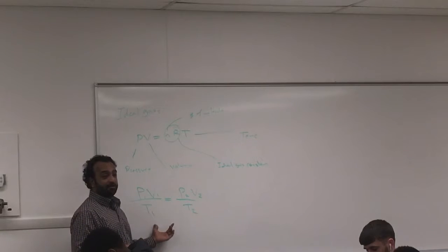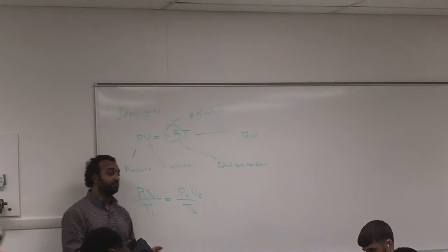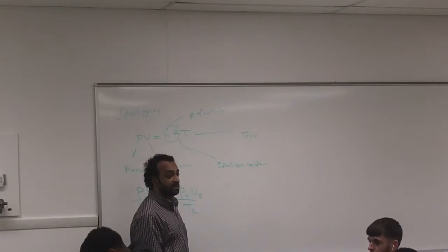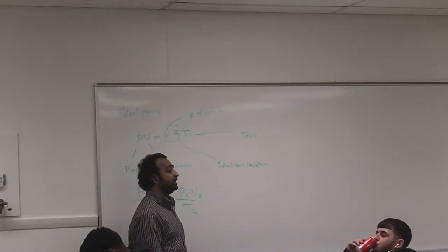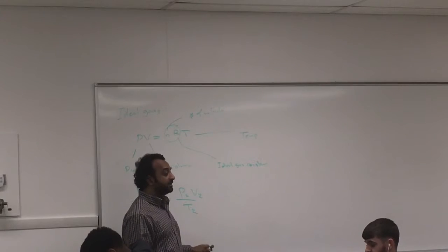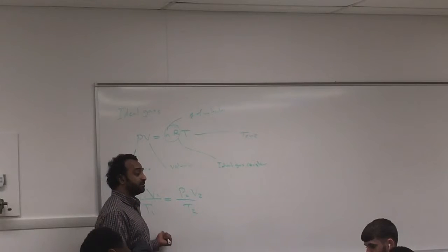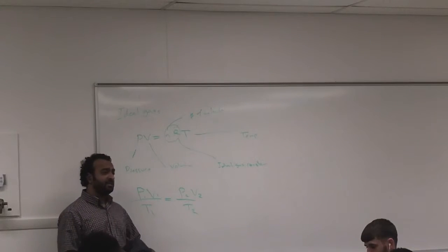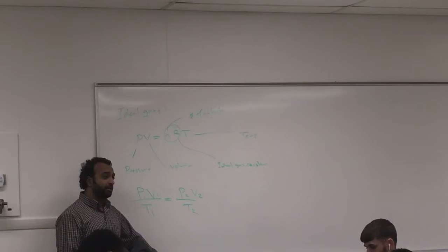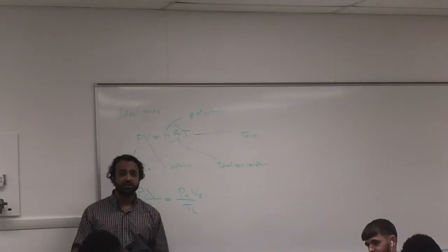So how would that play in our role? It's to calculate how much gas is going into the chamber. Because if we are running with gas, not oil, gas is compressible, and you want to know how much gas you're putting in there based on the volume, temperature, and pressure. Otherwise, how are you going to gauge the gas? And that's why the gas company charges you by BTU. Because if you think about it, will gas on a cold day be the same amount as gas on a hot day? No, it will expand. And they calculate for that error of expansion and temperature.